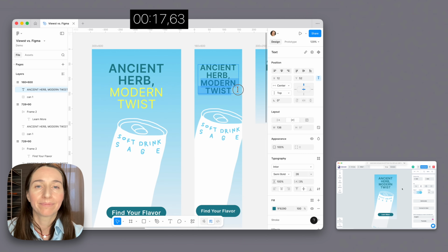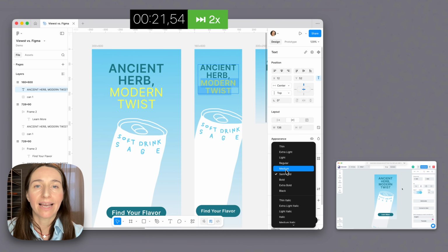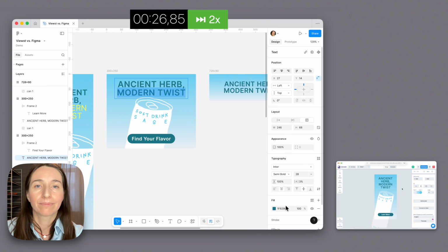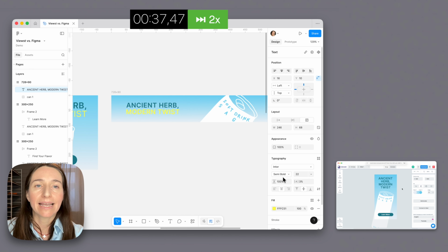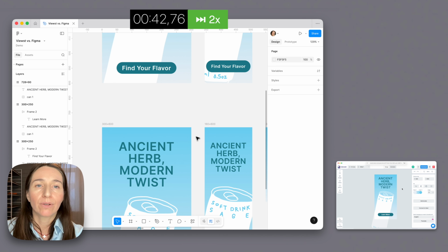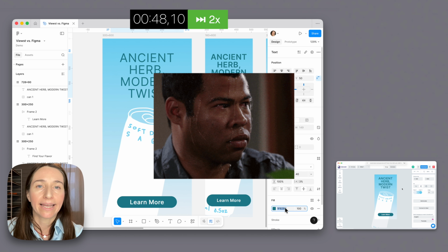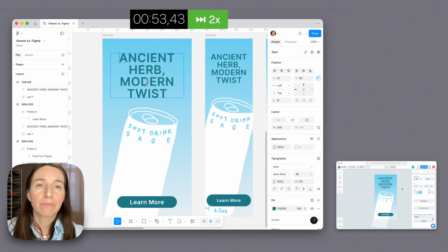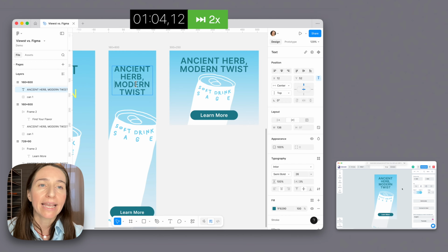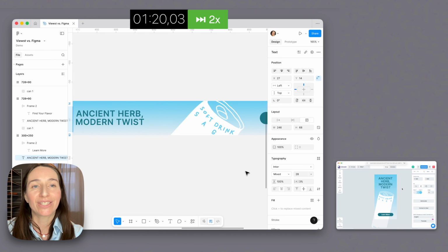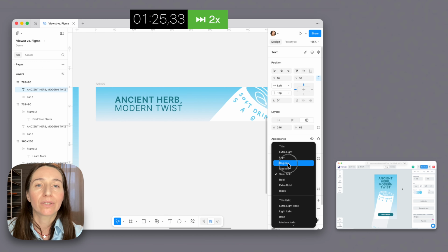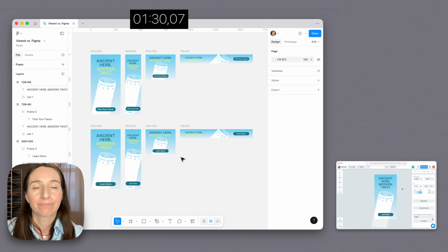Cool, one done. Now, I have to repeat that across all remaining artboards. I go through each of the other 7 banner sizes, select the same element on every frame, manually update the font and color again and again. And here's the fun limitation: Figma's multi-edit is great for changing the text content, but it doesn't let you bulk edit styles like font or color across different frames, the way we'd love it to. So all this just change the style everywhere edits turn into a slow manual copy-paste grind.